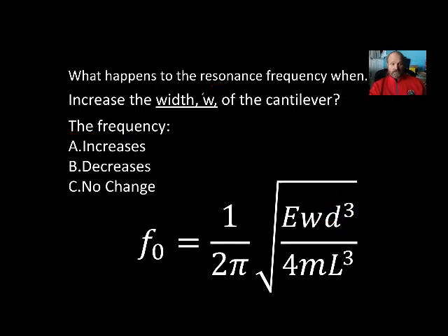All right. So now what about the width? And now in class, I would have you guys actually do this experiment with a set of cantilevers I've made. They have different widths, different thicknesses, and then you can decide how long to get it by how you clamp it to the table. And when you do this experiment, you would expect, just glancing at the equation, right? You'd expect that when the width gets wider, the frequency should get higher, right?